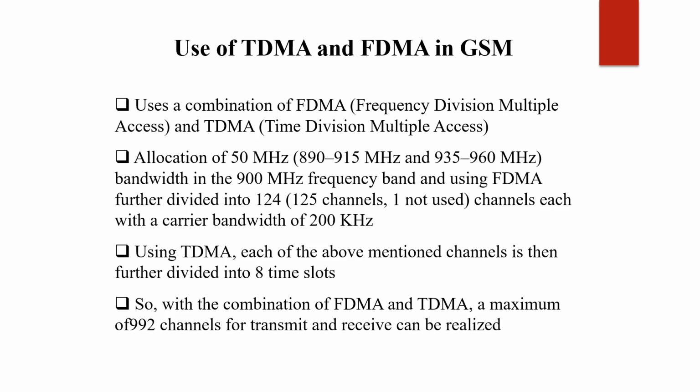We are going to see the details of the GSM system. This GSM system is totally based on a combination of two techniques: frequency division multiple access and time division multiple access. FDMA is nothing but frequency division multiple access, in which the frequency is distributed among a number of channels having a specific range, and also provided for a specific duration of time. It is the best suitable combination for a number of users connected in a single network.